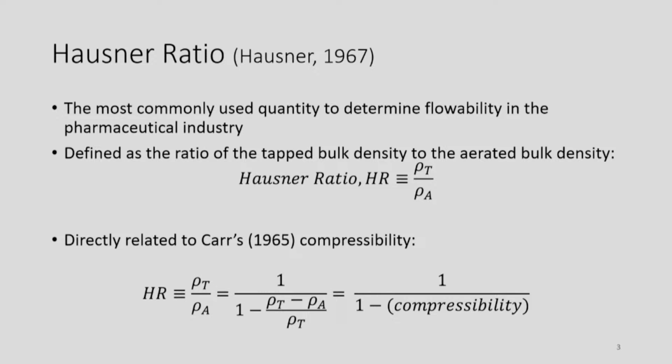So if the bulk density and the tap density are almost the same, then the compressibility will be low, right? It's not changing. When you tap, if there is no change in volume, then the bulk density will be the same as the tap density. But if the material changes in volume when you tap, if it's reducing in volume, then the tap density will go up, so the compressibility value will also be high.